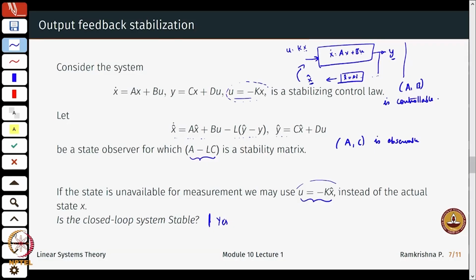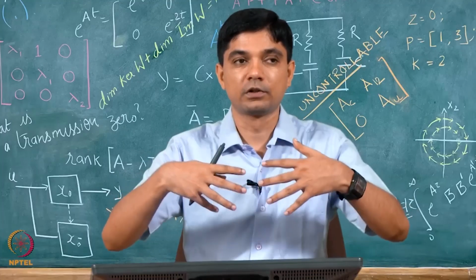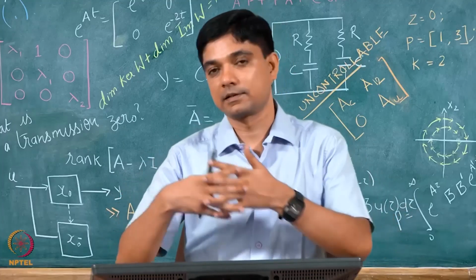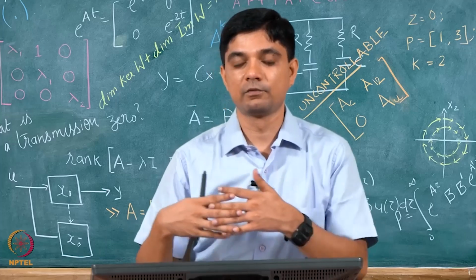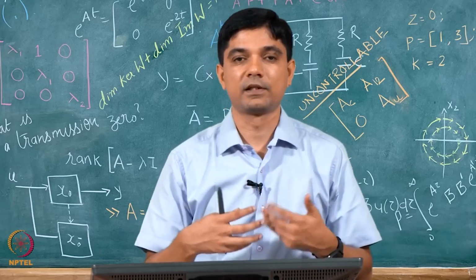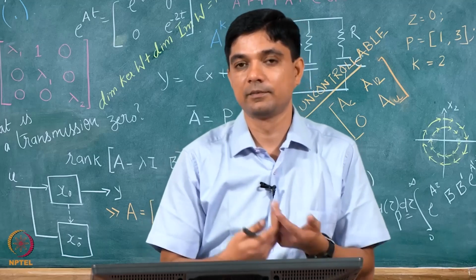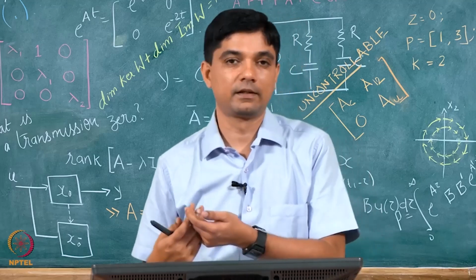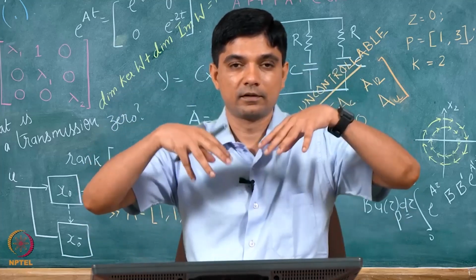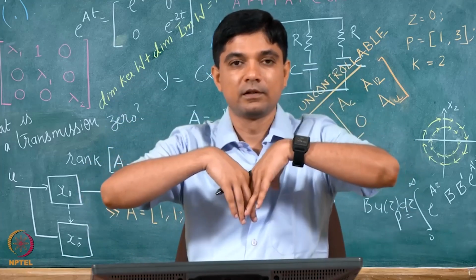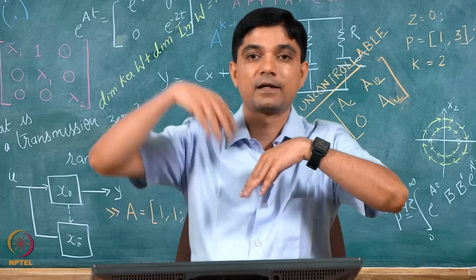One interesting thing to look at is when I introduce an observer in the system. Starting with the state feedback u equal to minus kx, I just have x dot equal to A minus Bk x, and I can do a bunch of things from stabilizability to pole placement and so on. Now, if I put on top of it an observer, does it really affect my original system?